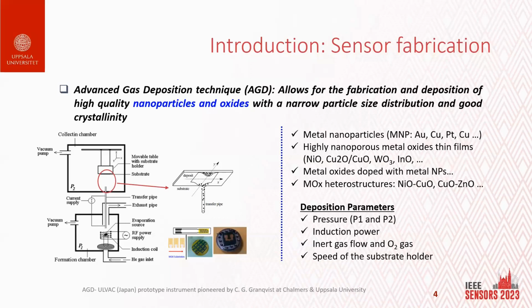There is a helium carrier gas, and there is also an oxygen supply. The vapor melt is oxidized with the oxygen, so that pure metal oxides are deposited on the substrates. You can have as many substrates as you want, not limited to silicon, alumina, or glass, on the substrate holder.